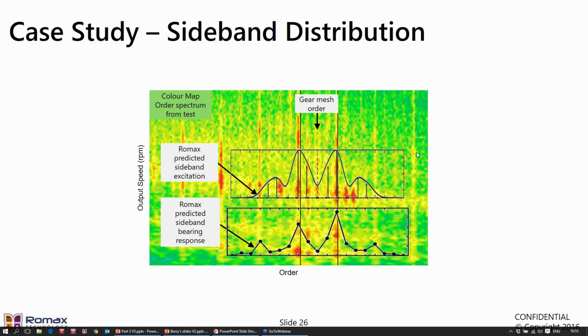Some people even try to move just 1 planet so that they're not even symmetric, and then you have to obviously look very carefully at the balancing of the planet carrier when you do that. But there are designs that nominally will give you cancelling of both radial and torsional forces. But remember, it's never perfect cancellation. As soon as we put in errors as well, we tend to destroy the cancellation, and also putting in errors also changes the phasing.